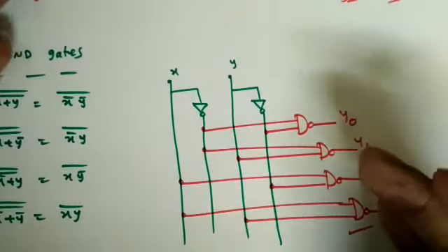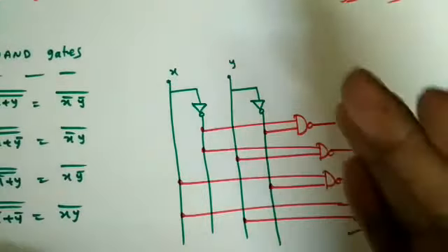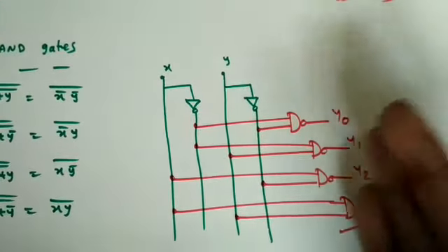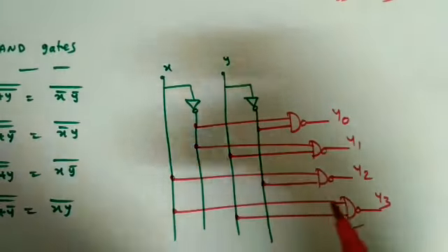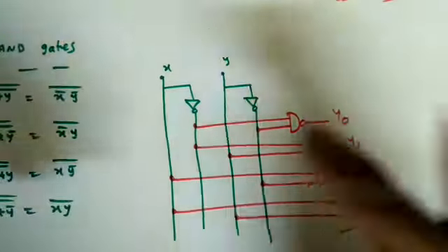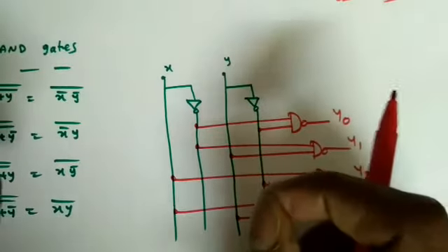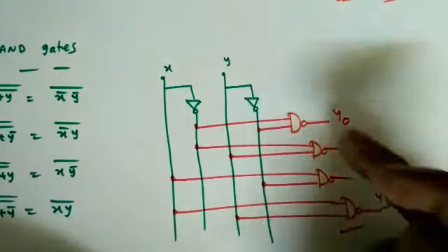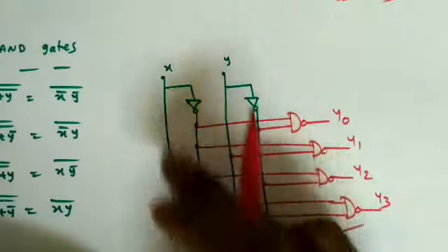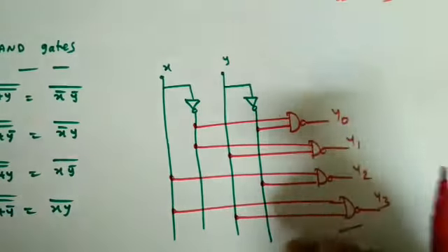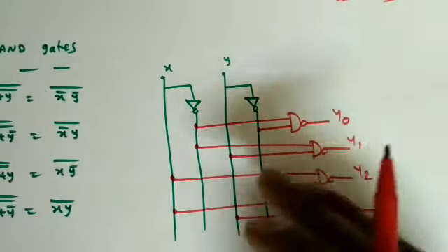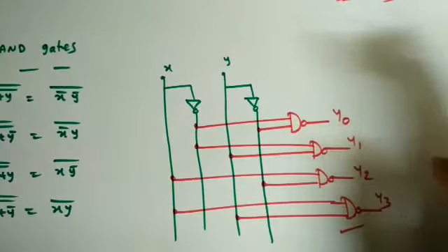Depending on the situation and the application, we have to use this type of gates. We may get questions on active low enable input or active low outputs also, so we have to be careful about them. Whenever there are NAND gates at the output side, we can say this is active low outputs. Then the truth table will be the opposite of the active high output.